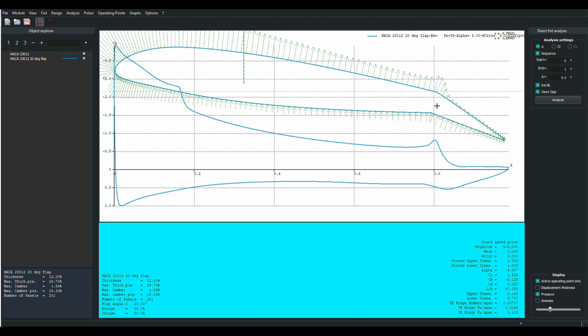And you can look at this in one simple way. If the control surface chunk were not attached to anything else up front, well, that'd just be a symmetrical airfoil with a round nose on it flying at a 20-degree angle of attack. So it's going to generate a lot of lift right at the front of that airfoil.